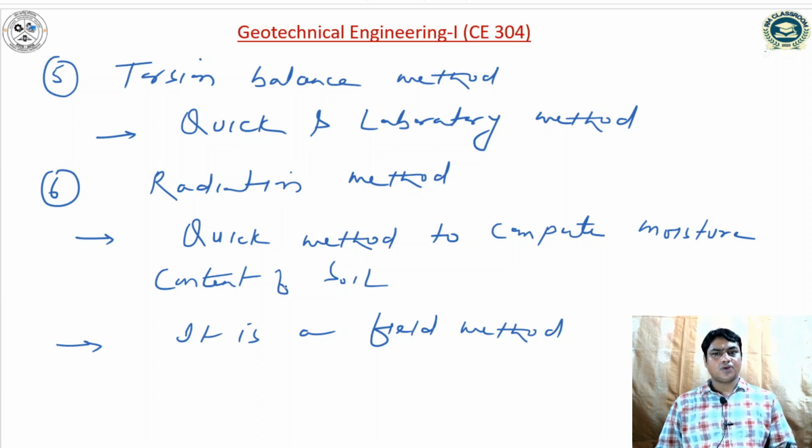For this you have to take a 900 ml picnometer bottle, and firstly measure the empty weight of the bottle, say it is W1. After that put the moist soil sample into the bottle and weigh it once again, say it is W2. After that fill the water in that bottle, say it is W3, that is weight of bottle plus moist soil plus water.